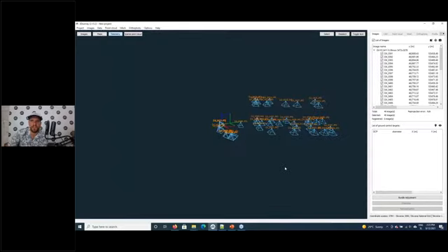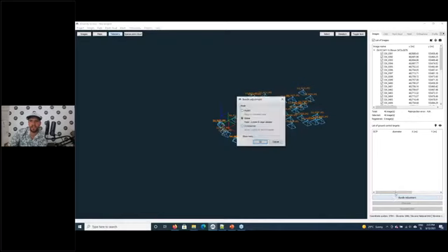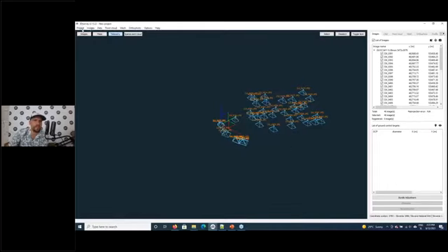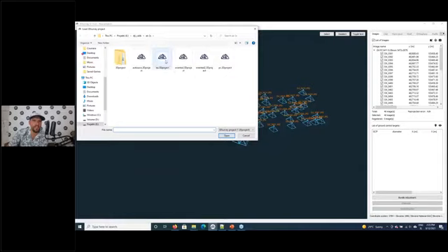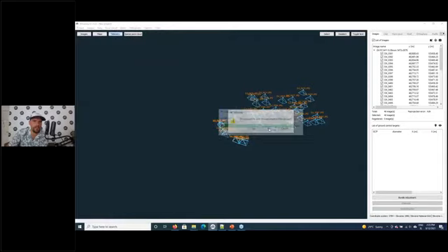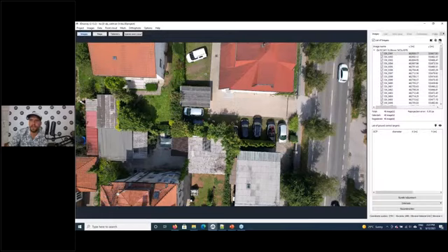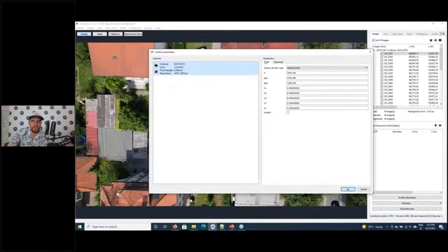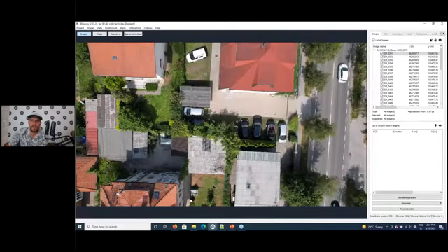Now, the simplest calibration is to do a first bundle adjustment with default settings and press OK. This would take now 2-3 minutes. In order for us not to wait, I will just load a project that has bundle adjustment already complete. After the initial bundle adjustment, we already got improved camera calibration parameters. Some distortion parameters were already calculated. Okay, that's perfect.